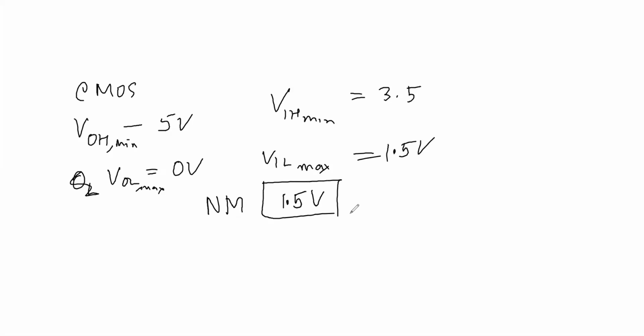So see the difference. For one characteristic we talked about the voltage levels and the noise margin. We have seen that TTL has only 0.4 volt of noise immunity, whereas CMOS has a much higher noise immunity of 1.5 volt. So CMOS circuits are less susceptible to noise. I think I'll not be able to take up any other characteristics. We are already late, so this is where I will stop. If there is any question I'd like to answer, else I'll take it up in the next class.